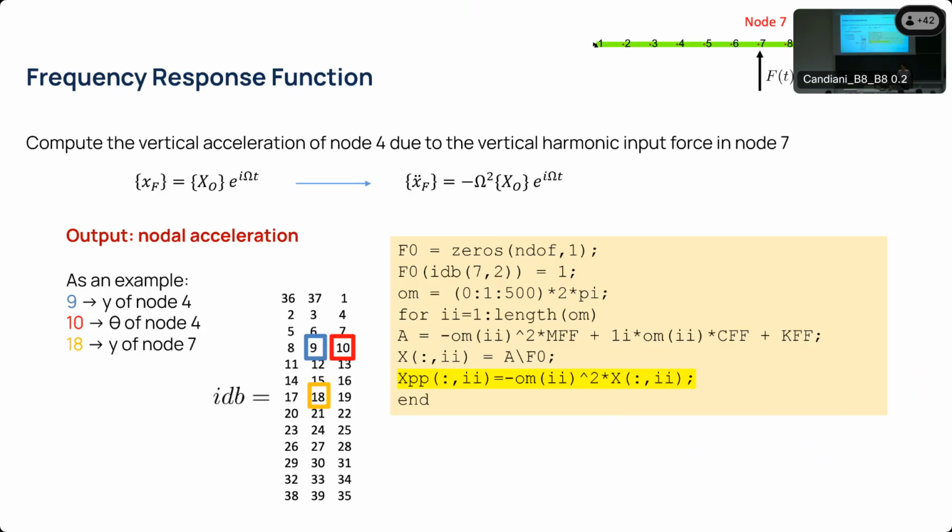Displacement against force frequency response function, but maybe you are not interested in the displacement. Maybe you are interested in knowing the acceleration of any of the 3 coordinates you want to investigate. How do we get from the displacement frequency response function to the acceleration frequency response function? You have to remember that in the frequency realm, the acceleration is just the displacement multiplied by omega squared.